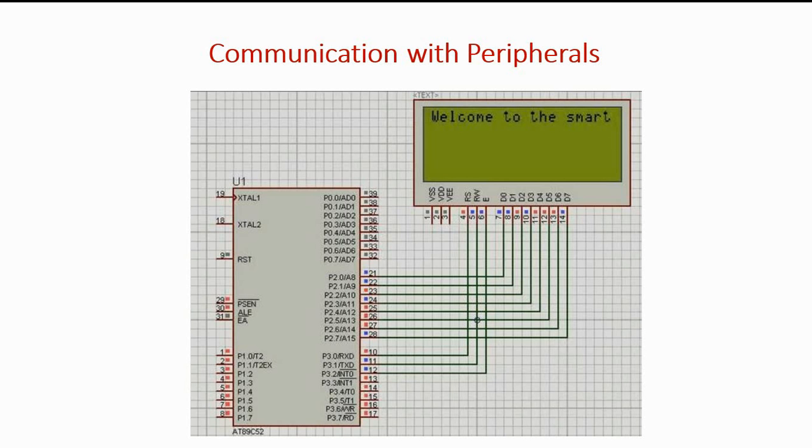A to D converters and D to A converters are also interfaced with the microcontroller in this way, by connecting all the data pins with the microcontroller. But in today's market, the A to Ds are available like 32-bit ADCs and 48-bit ADCs. So we cannot connect these ADCs with the microcontroller by connecting all the data pins. That's why some protocols are introduced to reduce the pin count.